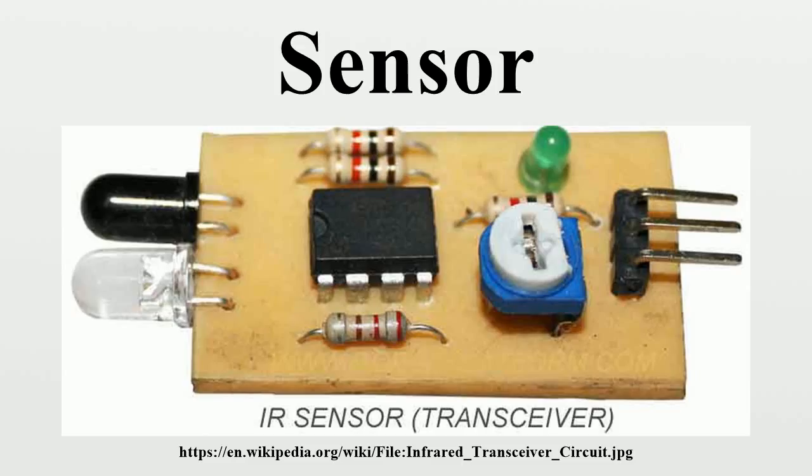Two main steps are involved in the functioning of a chemical sensor, namely, recognition and transduction. In the recognition step, analyte molecules interact selectively with receptor molecules or sites included in the structure of the recognition element of the sensor. Consequently, a characteristic physical parameter varies, and this variation is reported by means of an integrated transducer that generates the output signal.